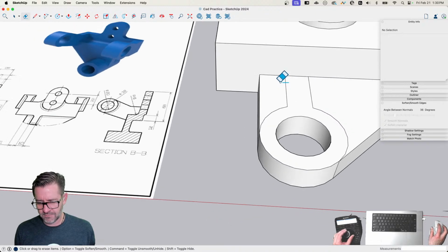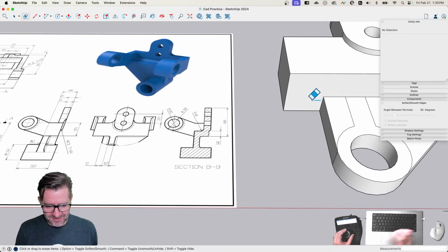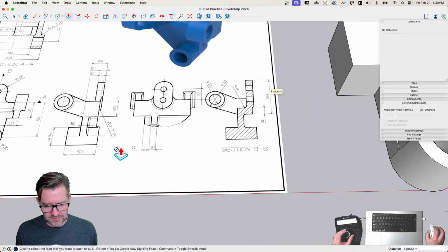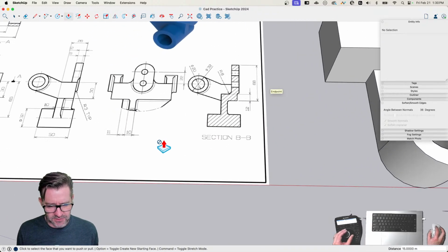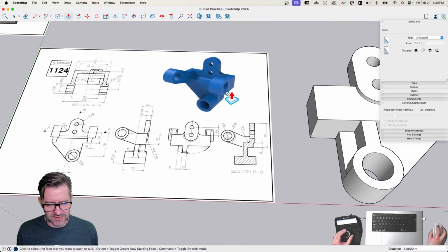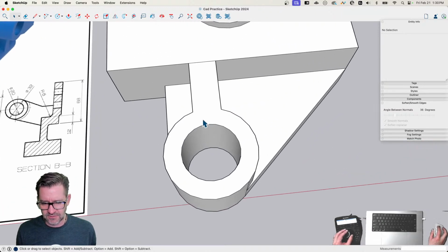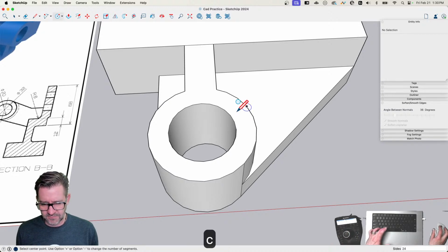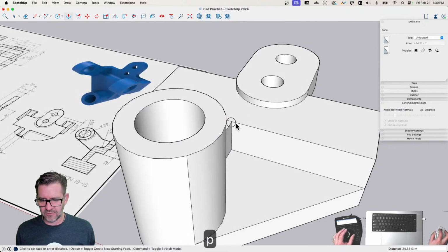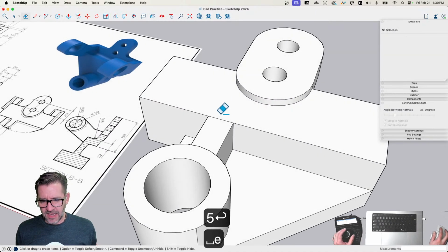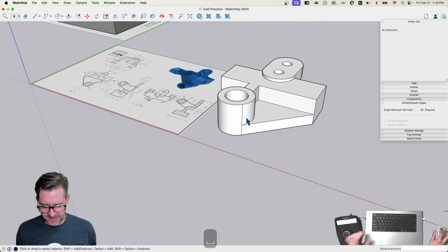Here's that face again. And then it's like that comes up to here, but then maybe the circle goes a little bit higher than this. So here's the thing I see. Right here, that's my 3, and this is saying 5. So I think that's just the circle. So I'm gonna draw another circle from the center to get that, and then that's gonna go up. That's 3. Yeah, so I'm gonna come up 5. I think that is the proper underside geometry.